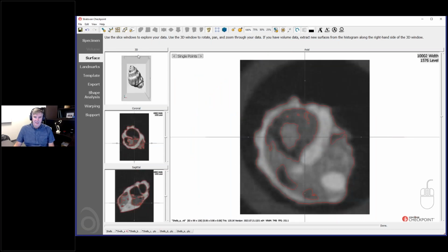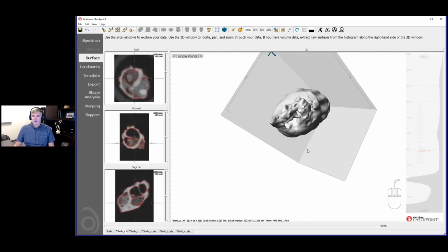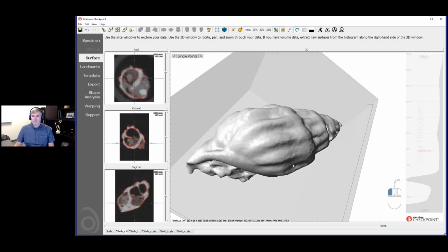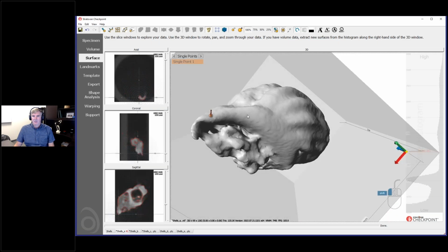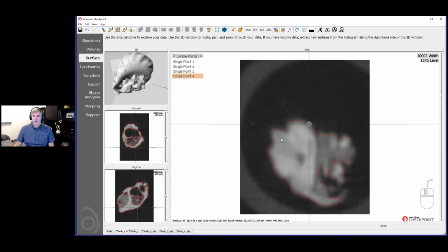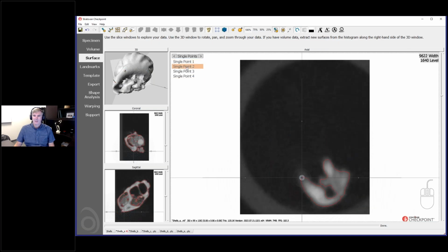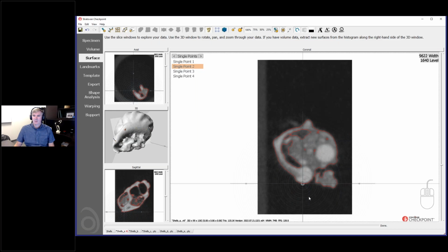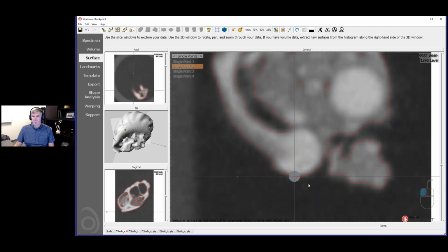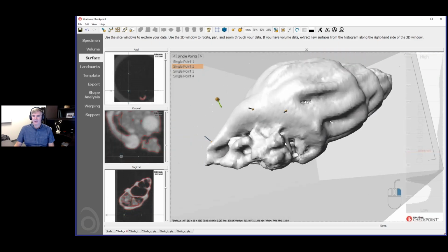This is where your volumetric data can be more helpful, because if I have a scan like this and I'm placing points on my surface here, I can go into the volumetric data and see maybe more precisely where that point lies on that surface, for example. Depending upon where you set your brightness and contrast, I can also change how the point appears. Here I moved it off the surface, so it's hanging out in space here. If I look at it from 3D, it's off in space.